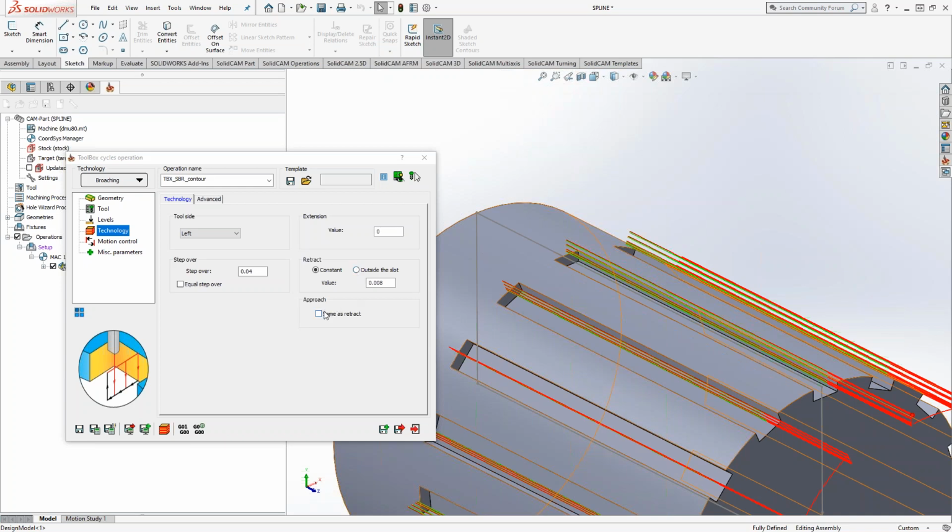But I've never run across where we have a blind spline like this being shown right here. Usually there's a relief on there of some sort. Yeah. Or what was it you mentioned last time? Was maybe the tool itself has some ability to address that, like the chip relief of it, or the chip breaker.